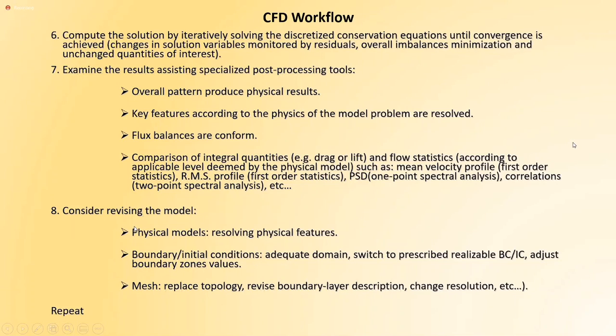We take the mesh, we increase it by a factor of 2, and we just check. Of course, the results are going to be different. They're going to be less accurate, but we check to see if the phenomenology still appears. If it doesn't, it means that we don't have the right resolution.